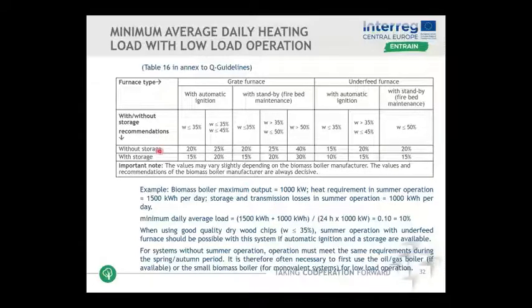This is very important because we expect that you have a system with a storage. Systems without storage, you should totally forget in the beginning. We do not recommend such systems anymore. Of course, you can build plants without storages, but this is only applied in very special conditions. So for standard conditions, a biomass district heating system without a storage is not state of the art anymore. So you should consider a storage. Very important, you should consider a storage with a control strategy. Your storage will not help you much at all if you do not include it in a load management and control strategy.